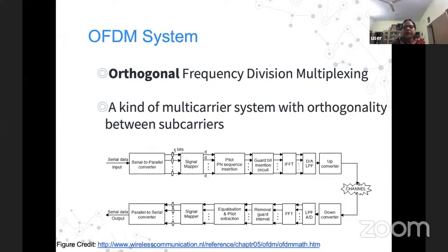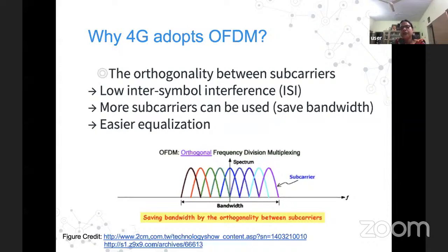No one will guarantee that your system will give you strict orthogonality. Even if you maintain your electronics perfectly, and even if the ambient temperature is working in a quite natural way, even then there is always a problem of intersymbol interference and intercarrier interference, and the main problem is strict orthogonality. Suppose some deviation is there from the transmitting frequency to the receiving frequency, sine of omega naught t plus delta of t.